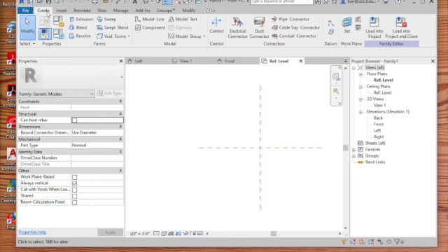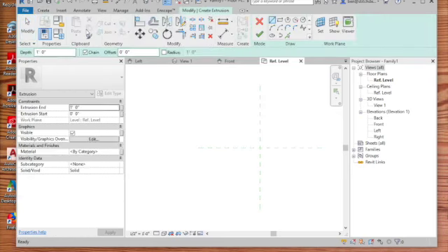And now select the Extrusion tool. This should enact the Family Editor function. So all of your modify tools and drafting tools that you used in your first exercise should come up and be familiar.